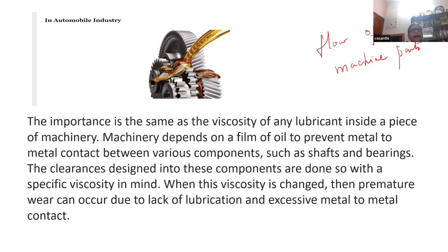Viscosity increases, and what will happen to the moving parts? Will they not get jammed? Yes or no? They will get jammed because of high viscosity. So you have to change the type of lubricant according to whether it is summer or winter. So the variation of viscosity should be kept in mind.